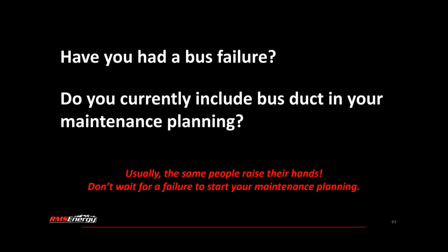Okay, we'll go back to high pot testing. Can you talk about the differences and or the benefits of using a DC or an AC high pot test? Yeah, so both are generally acceptable tests. IEEE specifies AC almost primarily now for both switchgear and bus duct, but that's really for the design testing.